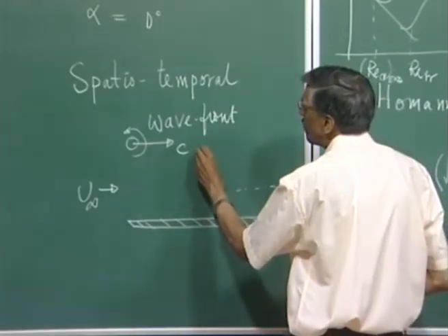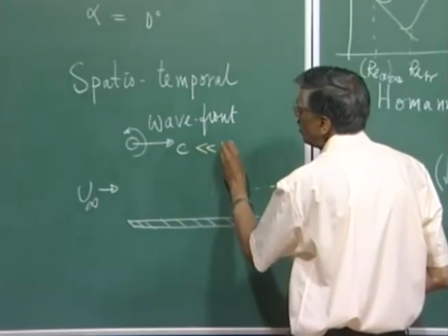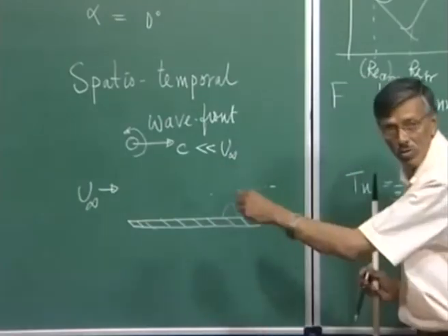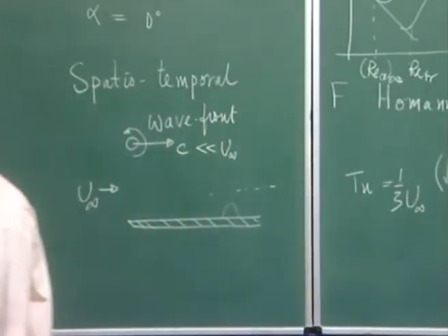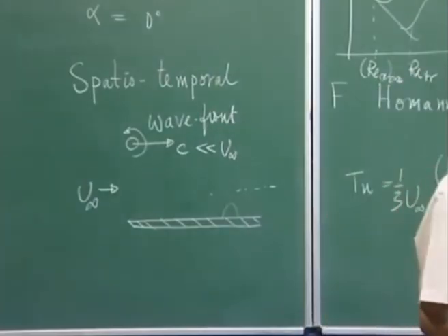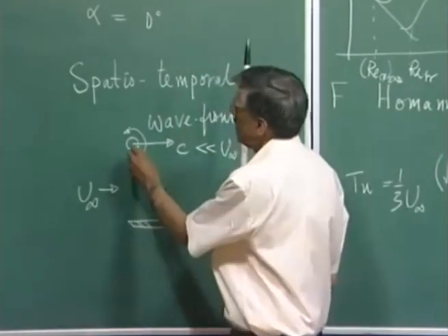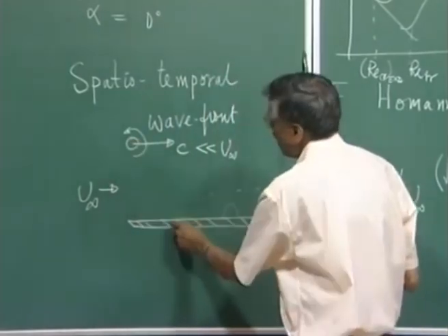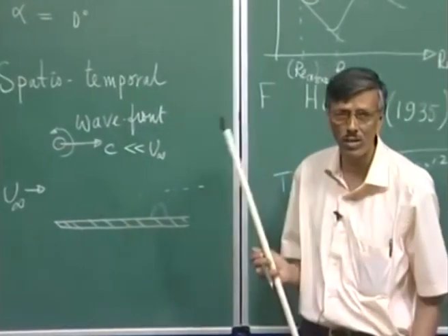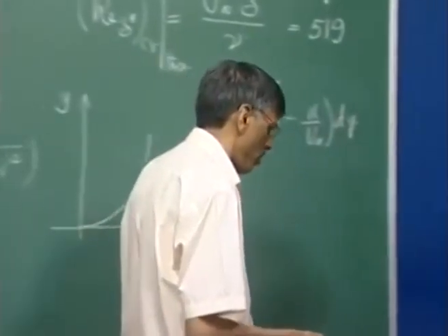If c is much smaller compared to U infinity, you would notice some kind of bubbles forming, and they also propagate like what you are seeing here on top. So, this is what we called a vortex induced instability, because we have a definitive vortex there, and that is linking with this boundary layer. This vortex actually destabilizes this shear layer. So, this instability is called the vortex induced instability. So, we have various mechanisms by which we can see this. Having given you this overview,